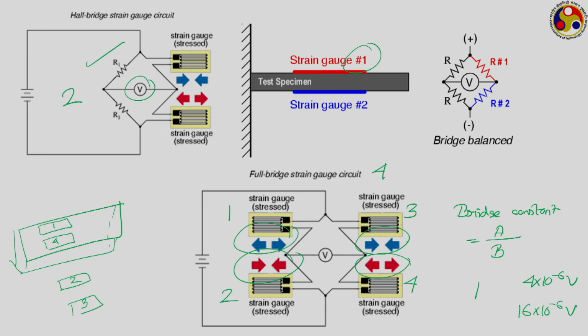So, these two are the two most important kinds of electrical circuitry that are used in conjunction with resistive strain gauges, the ballast resistor and this bridge circuit. We have a third one which is called the simple constant current strain gauge circuit, but today I do not have time. So, I am finishing the discussion here itself for the day. The simple constant current strain gauge circuit we shall be discussing in the next discussion.